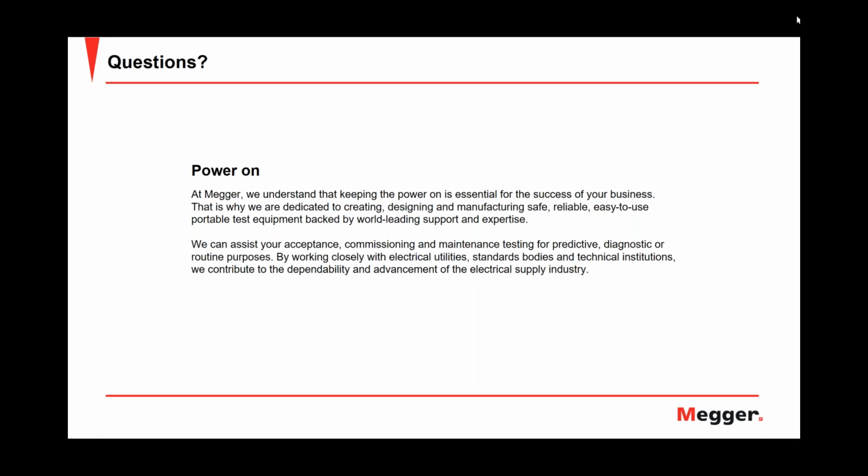The DC source has one other effect on a breakdown test, because a breakdown test means I have a fault, so I have somewhere an air gap in the medium voltage cable. And when you apply DC, you always have this additional effect of ionization of the air. As you keep the DC voltage on, the air starts to ionize, and then the air breaks down earlier at a lower voltage and flashes over. So the fault locating application for DC is very different from the test functionality.